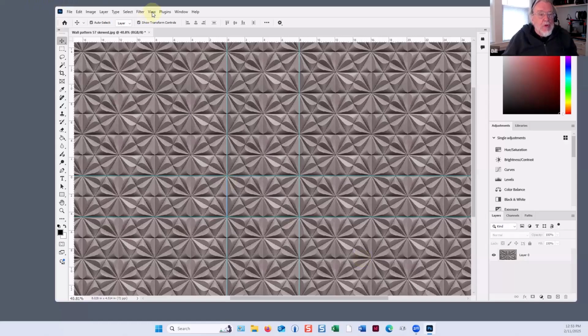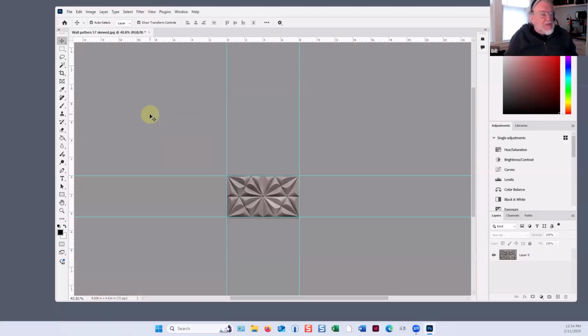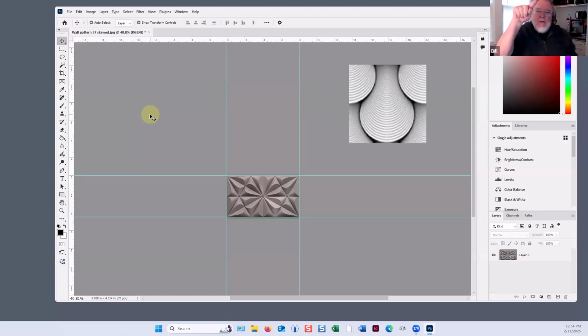And we can turn View, Pattern Preview off, and then we can use this in Revit as a basis for a material, the way that we did last week with a couple of those different patterns we looked at, like that loopy thing and a couple others.